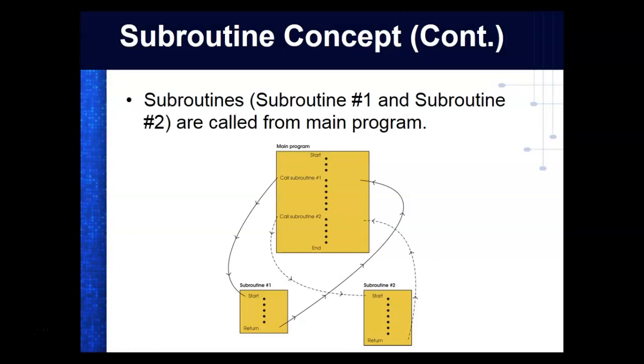So we call subroutine 1, we call it calling. So when a program asks for it to run a subroutine, it says that we're going to call that subroutine. That's the term that we use. So we have a subroutine instruction. It's called JSR, jump subroutine. We put it inside the program. We go out, we write our individual routine the way we want it, and then we would come in, and when we run it, we just call the subroutine. It goes out there, runs the subroutine, scans through it one time, and it comes back to the main program.